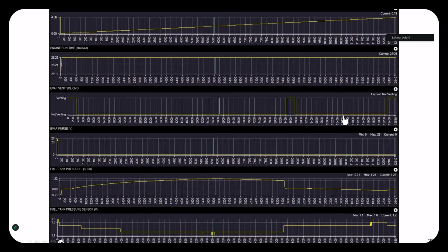Okay. And here's an example of a key off system. This is from a GM. We're focused on GM right now. Notice what it says. This one started the testing about 5 minutes after shutdown. You take the key, you get out of the car, you walk away. You don't even realize it. You just drove it for almost over 28 minutes. That helped build up some pressure in the tank. The computer looks at that. After so much time, it turns the system on.